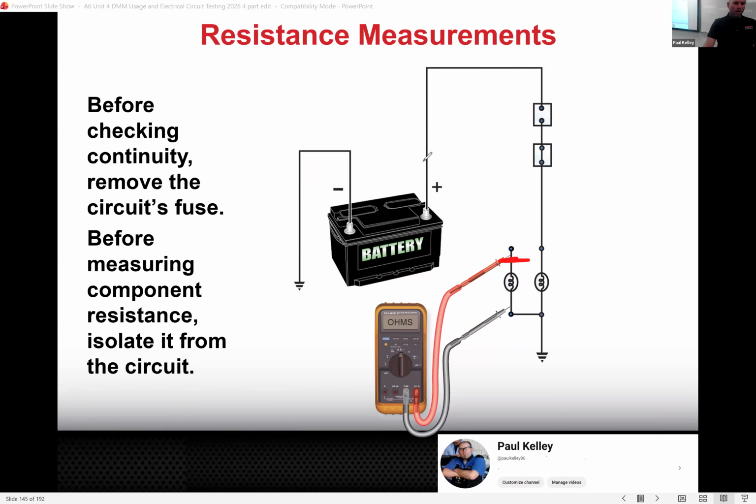Cool. And then here was that application you asked about the voltage. We check voltage mostly. In fact, let me delete that. If we check voltage mostly, I agree. Here's when we could check continuity. Like we could measure the continuity of that bulb. And honestly, if you wanted to start with ohms, you could check the bulbs with ohms. It's just, remember, like I was saying many times, checking resistance isn't as accurate as checking voltage, so I would go with the voltage. Cool, it's a dynamic test.